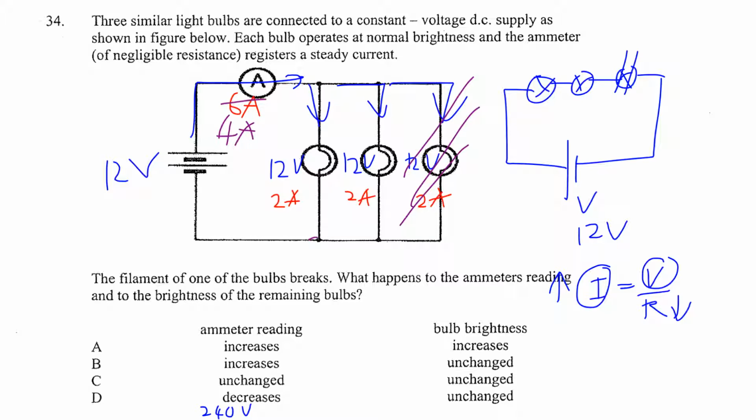So if it increases, then your total circuit current will decrease. That's why it must drop. You understand now? The total circuit current cannot remain the same, because the total circuit resistance has increased. Okay now? Now if you connect them in series, then what will happen is, for example, some people ask me